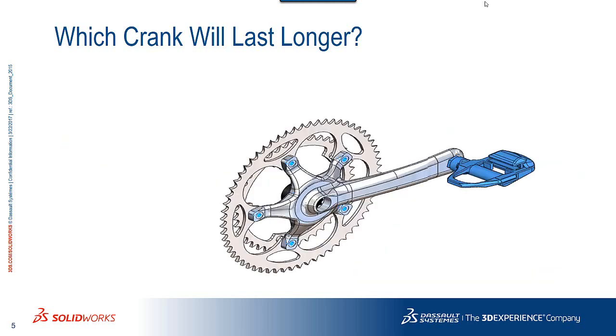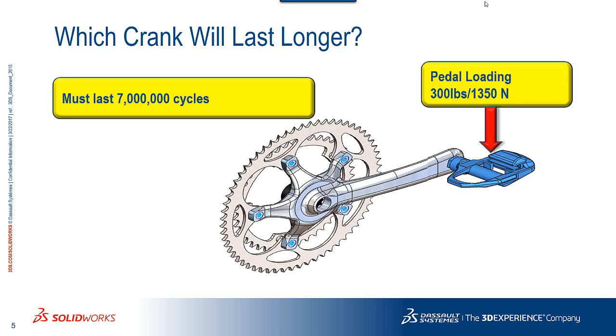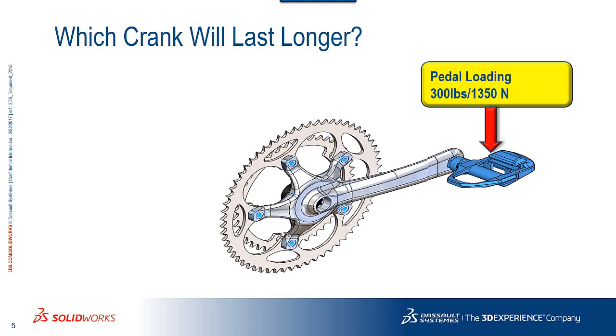To start with, let's take a particular design which is created using experience and see how simulation can help to meet our goals. The pedal is subject to a loading of 1,350 Newton. This is the force that the rider puts on the pedal. Our goal is to have the pedal sustain 7 million cycles, which is considered infinite life.